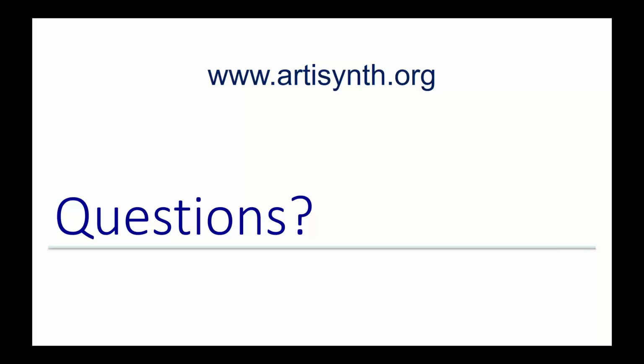Thank you. I think there's also viscoelasticity, I should also point out that a material property has a couple of functions you provide: compute the stress and compute the tangent matrix. You can write your own component that does that, and then you have your own material. So if you have something interesting that you want and you know how to do it, then it's relatively straightforward to incorporate that into ArtiSynth yourself.